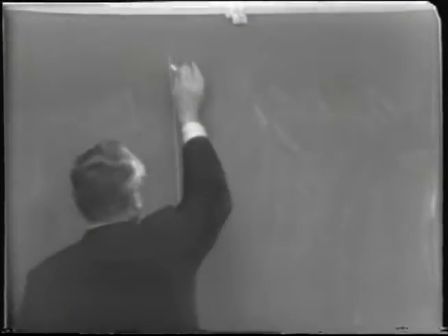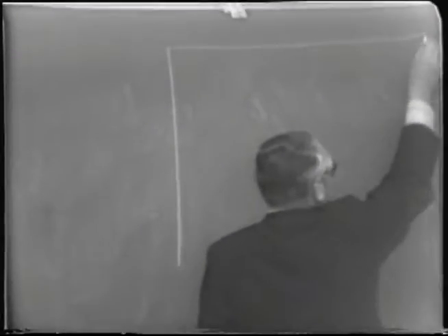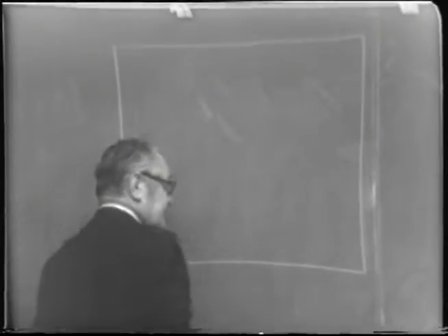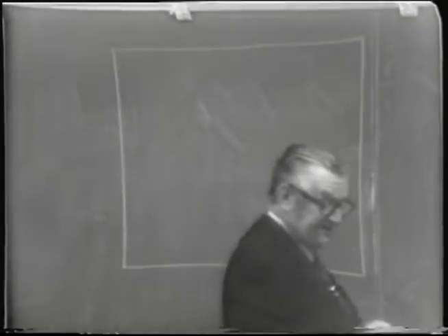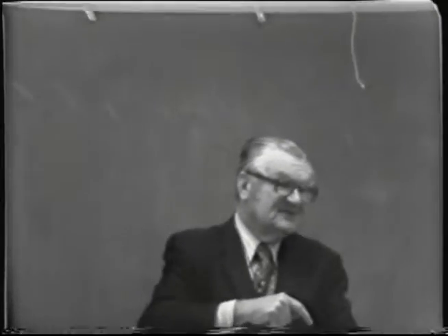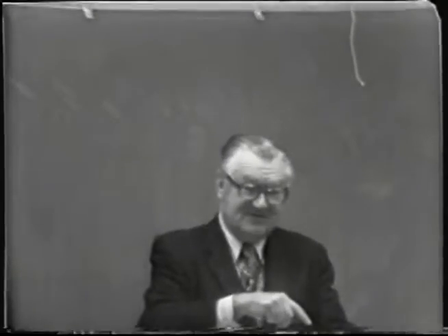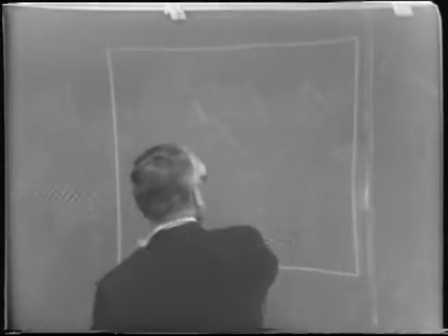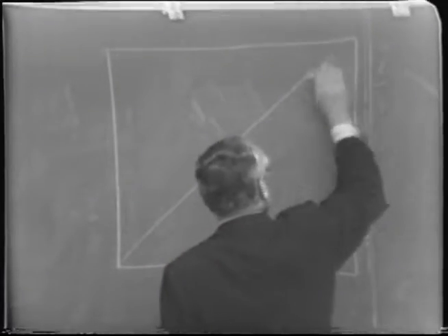In fact, in several textbooks, you'll find examples of these kinds of problems worked out, and they'll determine the number of ideal stages, and then they'll say the number of trays is one minus. Take off one for the still pot. Because let's say we have a simple case here of a